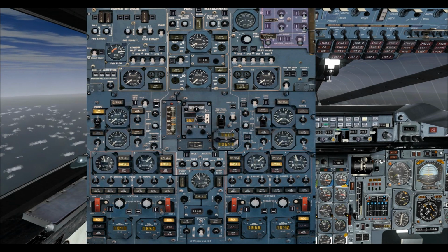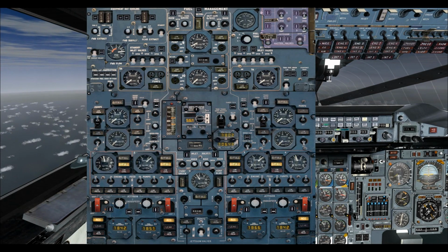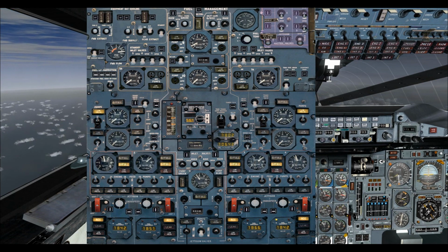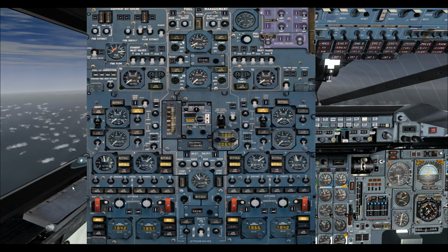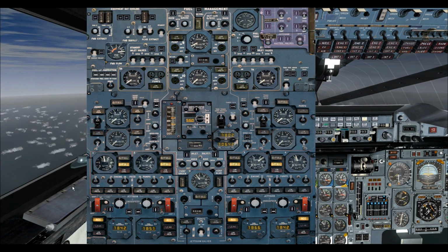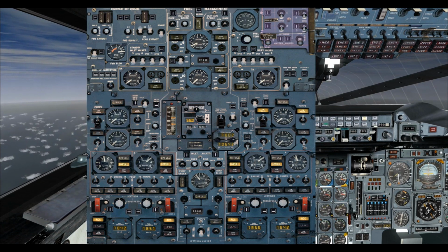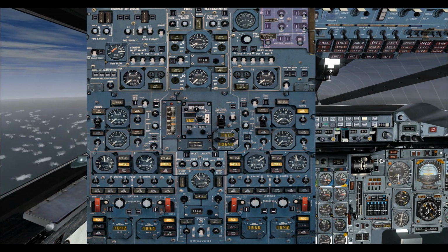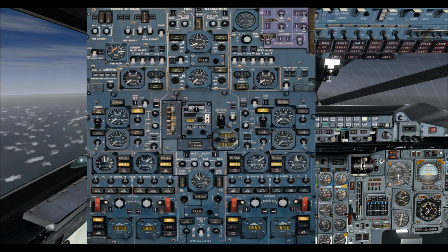We've just now passed through Mach 1. We're continuing our descent, and just checking on our fuel panel, we can see that the collector tanks 1 to 4 are filling up. Fuel is pumping out of tank 11, 5,000 kilos to go, and our CG is at 56% and moving down. As we approach the end of the transfer, I'll be back to give the final numbers.